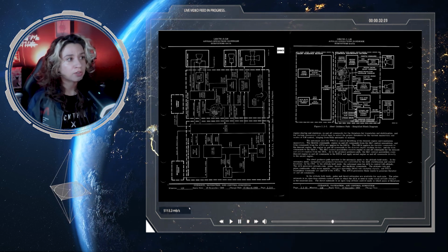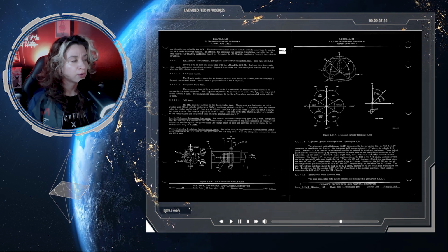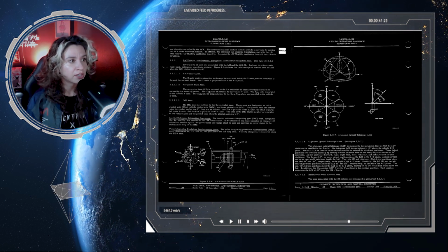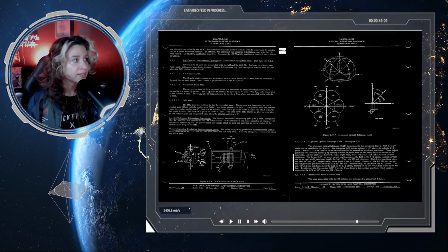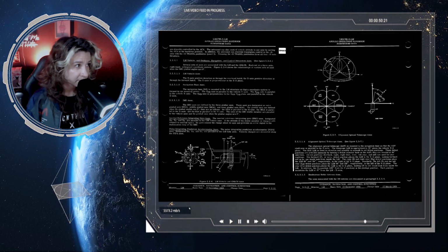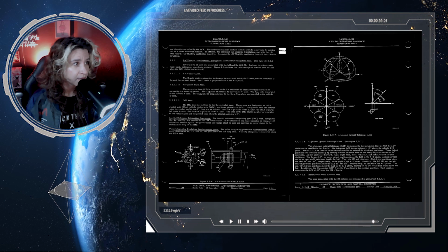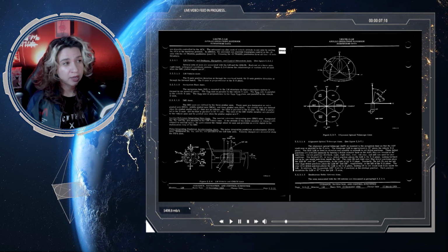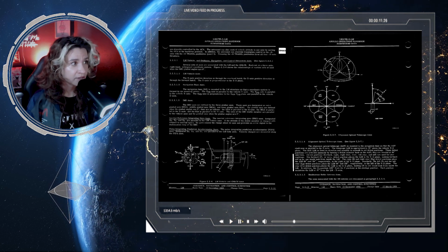The astronaut can also control vehicle attitude in any axis by moving the ACA to the hard-over positions. In addition, the astronaut can override translation control in the plus axis, negative axis with the plus X transl push button, see panel 5. Pressing the positive X transl button fires all 4 positive X-axis thrusters.